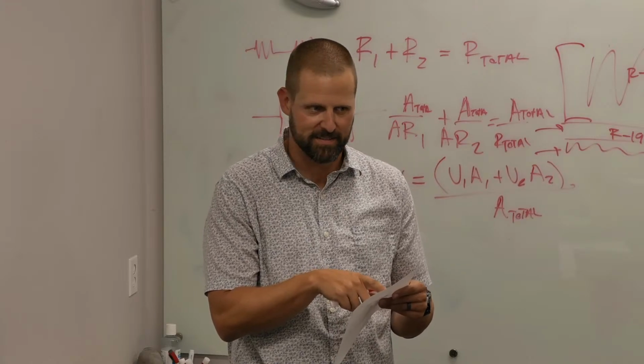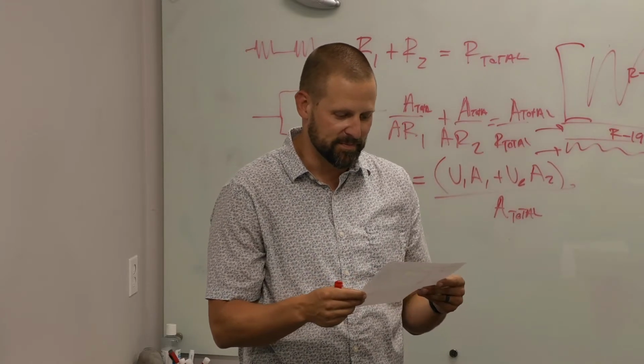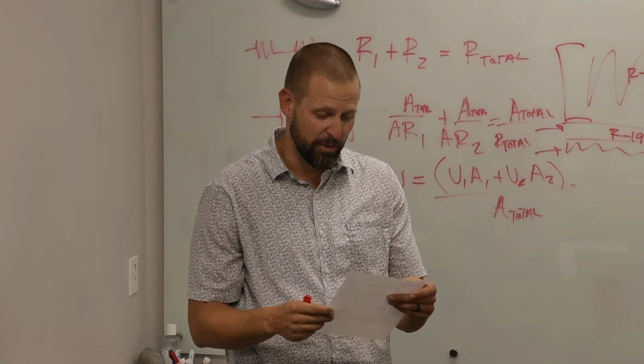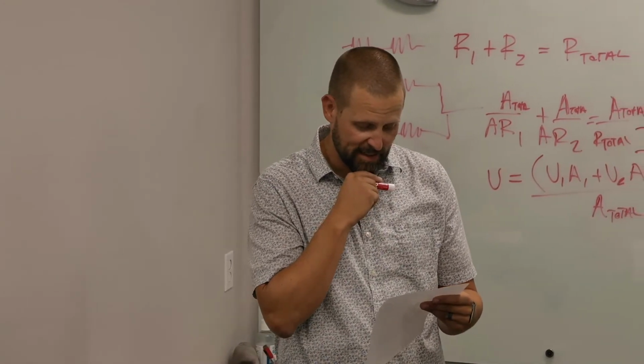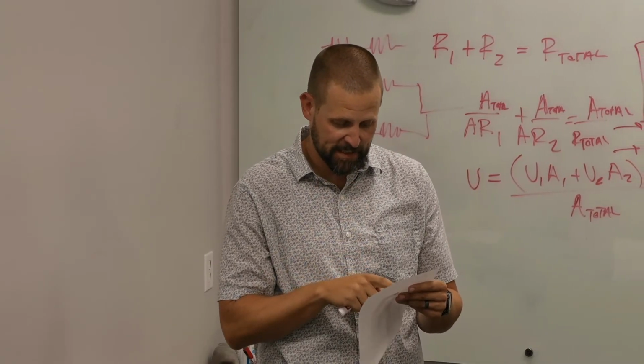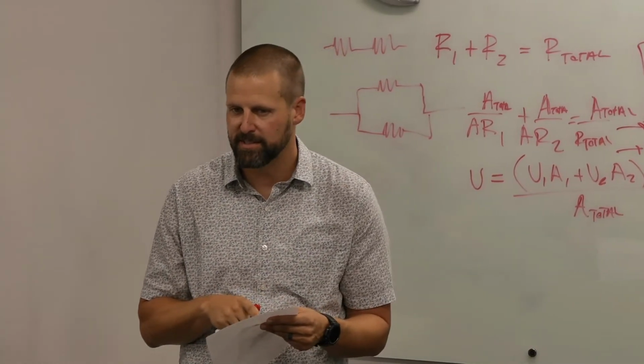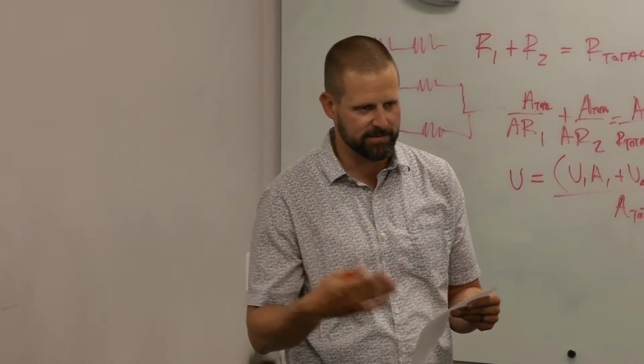Does that make sense? Yes. Okay. So that's an R13 cavity insulation assembly. So that's a U factor of 0.217. That'd be like an R value of 5. We're kind of rounding.